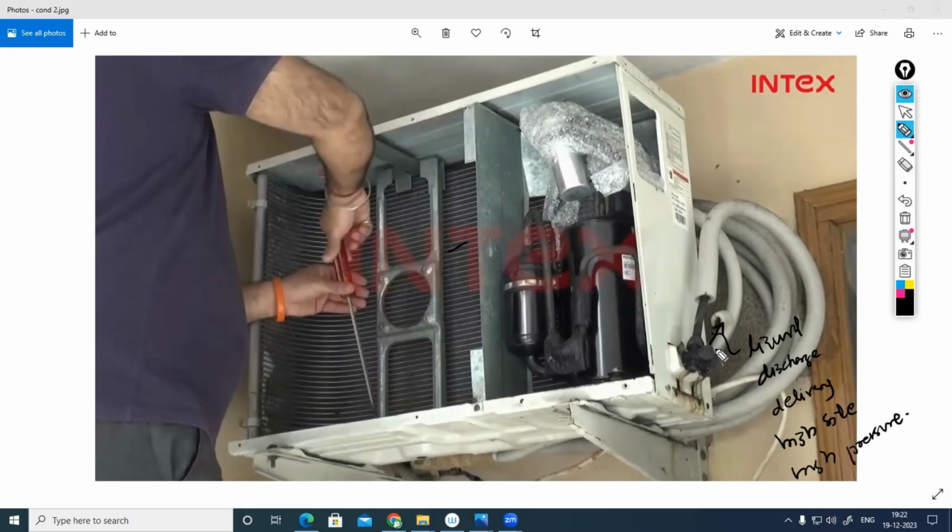So pressure in the liquid line is similar to the compressor delivery pressure only. With respect to the type of refrigerant, the compressor delivery pressure and the suction pressure ranges will vary. But irrespective of capacity, whatever the ton, for example, if you are using R410A as a refrigerant, sometimes the delivery pressure might be 42 bar, suction pressure might be like 15 bar.